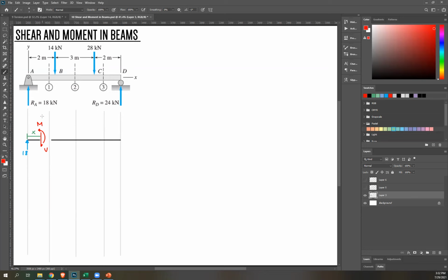Okay? Then next, if you want to isolate the right side, remember your Newton's law, or just the method of members. When you assume direction for one end, the connecting member should be the opposite of that. So this is a connecting member. Shear force downward here, so here it should be upward. And then here, moment. The opposite of that would be this. So this is your M.